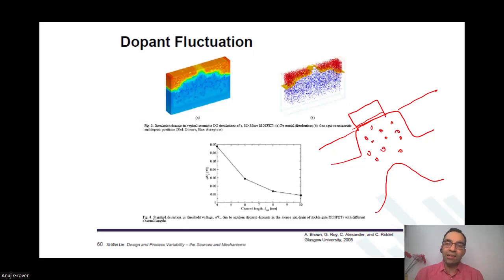To do the worst case analysis, you may say that, okay, I have to assume pass gate to be at 3.5 sigma, pull down to be at 4 sigma away. And that is my worst case. That was what we did in this SNM analysis, and in the write margin analysis also in the previous lecture. So we placed devices at the worst places and we saw the impact. But it is not that this is bound to happen exactly this way. We just want to be sure that statistically we are safe.